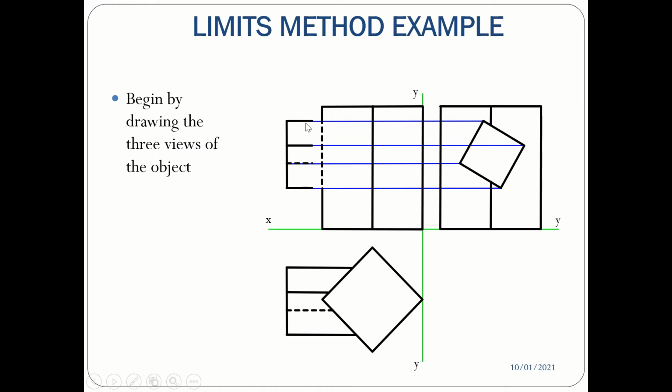So this guy up here that the cursor is on at the moment, that's the highest one up there. The one that is here, that is the closer edge to us, that is down here in plan view. The lowest one must be the one down here in hidden detail. And this one here that's in hidden detail in elevation is the furthest one back, and that is that guy there. So I highly recommend you label your views, because if you don't, you'll get lost later on as they get quite complicated.